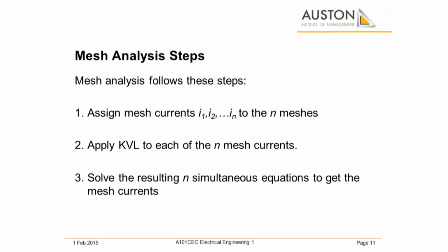The first one is to identify the loops, and we are going to assign mesh currents to these meshes. Next, we are going to apply Kirchhoff's voltage law to each of these mesh currents. And with the resulting simultaneous equations, we will try to solve for the mesh currents using any mathematical techniques.